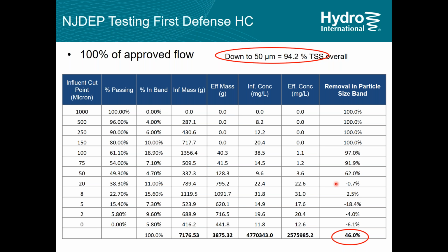Once you drop below 50 and head down to 20 microns, and we've known this for years, swirl separators would have to be enormous to work in this area. So from a practical point of view, and everyone wants the smallest one they can get, anything below 20 microns, or in that 50 to 20 microns, you're really starting to look at filtration. And we found this was consistent with different pieces of equipment we tested, that at the 50 micron range, that's when these separators really start to struggle.